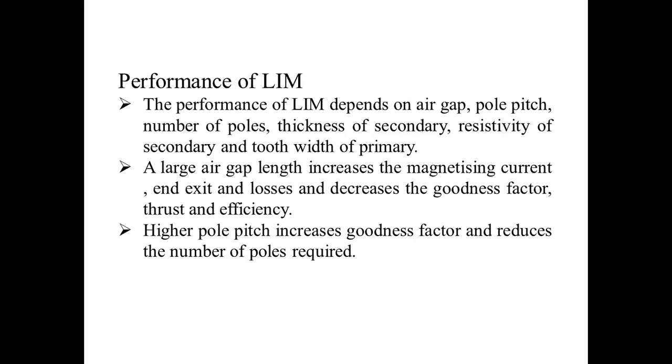winding. Next, the performance of the linear induction motor depends on the air gap, pole pitch value, number of poles, how many poles are placed, thickness of the secondary side, resistivity of the secondary, and tooth width of the primary.